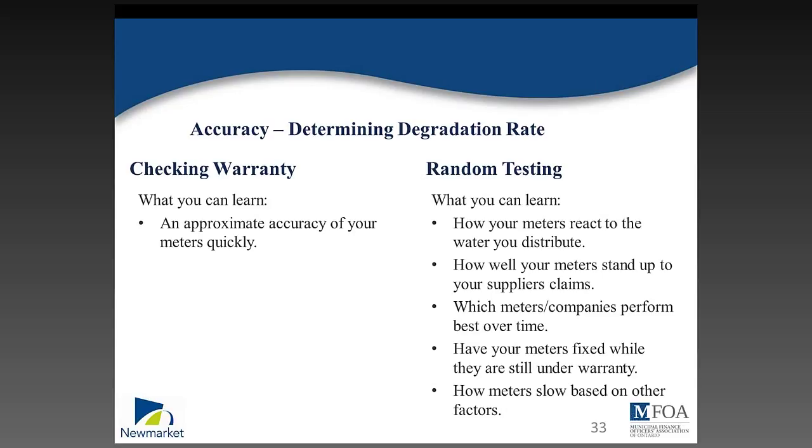Age is proving to be not a very good indicator. Actually, water flow creates much more wear and tear than actual age. And so you don't really know how well your meters are performing until you test them. Now, some municipalities do testing programs, but it's on a reactionary basis where they only test when customers complain about the measurement. But customers aren't likely to complain about it measuring too low. They're complaining about it measuring too high. So you can't get a good idea unless you're randomly testing your meters.